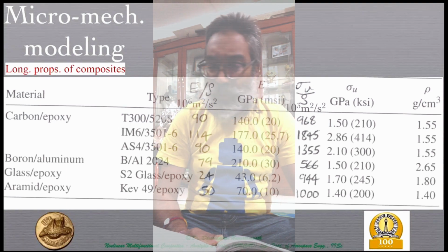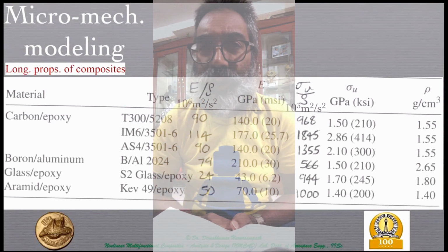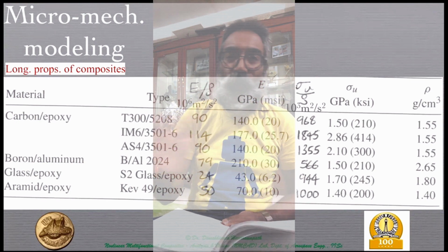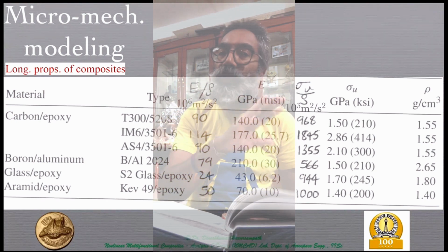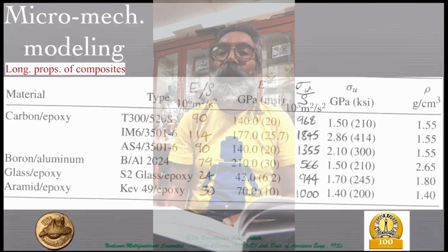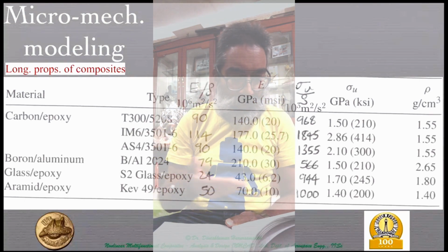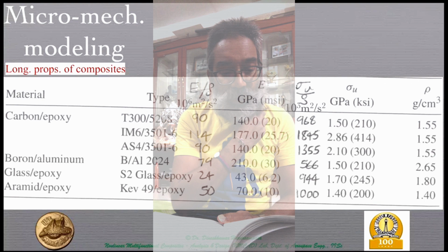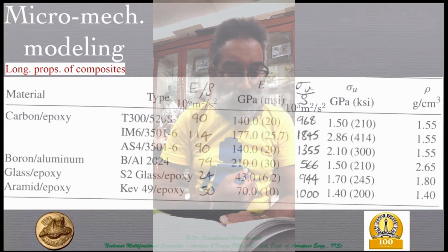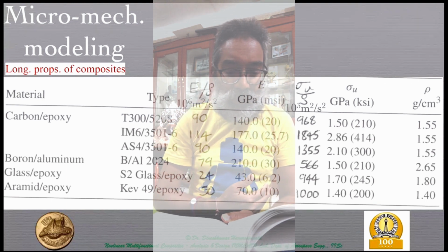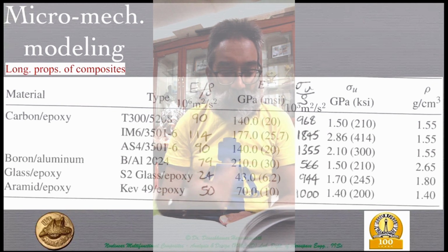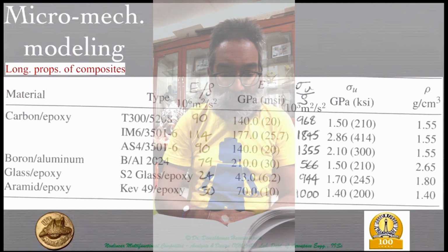And you can see that the Young's modulus rarely changes for any given type of alloy. Most steels will have around 210 and most aluminium alloys will have around 70. So in this particular case, what is listed in your textbook is about 72 gigapascals as the Young's modulus for 2024 T3 and 71 gigapascals for 7075 T6.